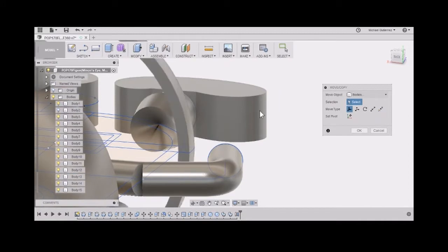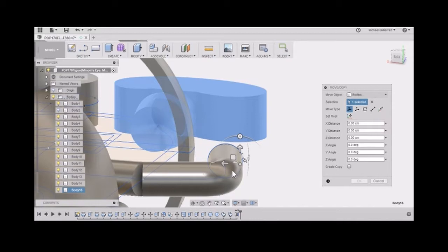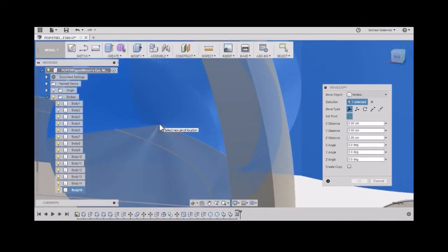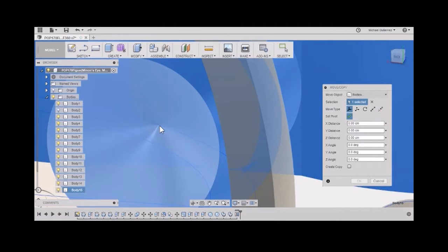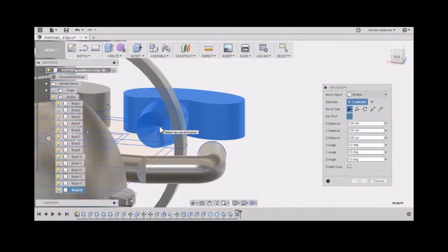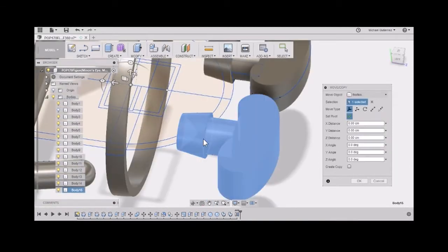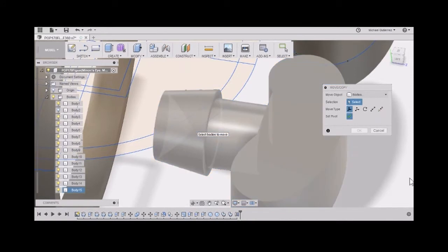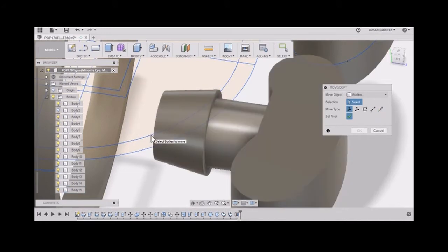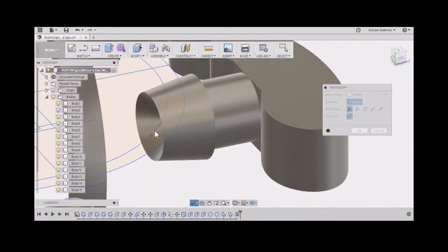before that, select your whole body. So select this body. Now it's right here, and we want this to be right there. So you're rotating on this axis. Hit select pivot. You select where you want the pivot to be. I want it to be right here. If it wants me there. You just gotta fight with it a little bit.